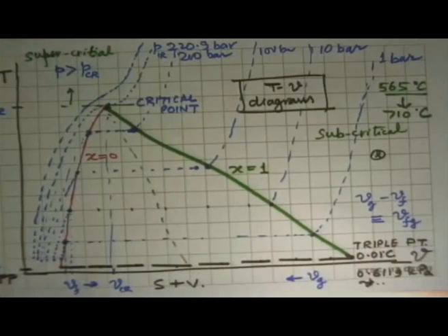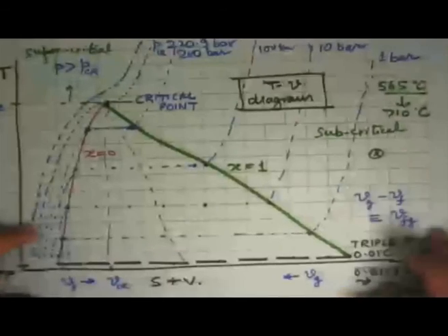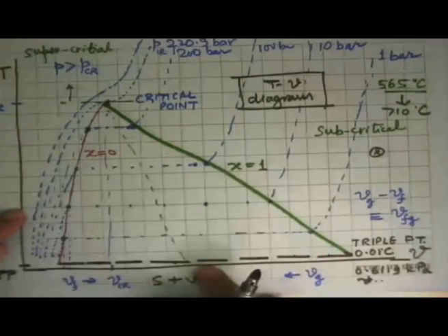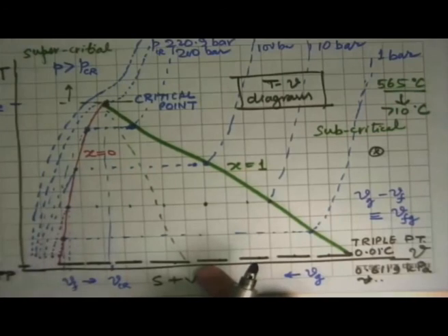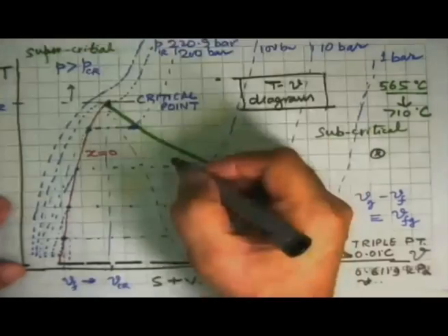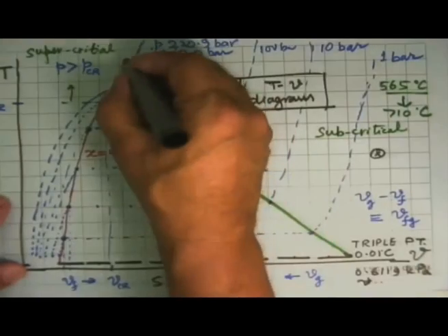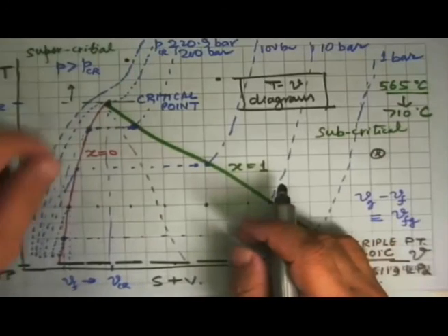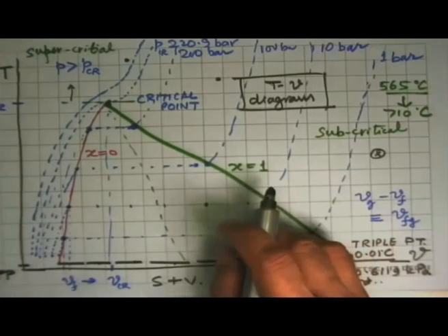And it gives us the ability to tell what will be the state of the substance once two independent properties are known. So if we can locate that the state is, say, here, we know it is a wet saturated state, we can figure out where is the temperature, what is the specific volume, and then calculate all the other properties also. If the state happens to be here, we know this is superheated state. If the state happens to be here, you know this is a supercritical fluid or a dense fluid, we know what the specific volume, entropy, everything else is there.